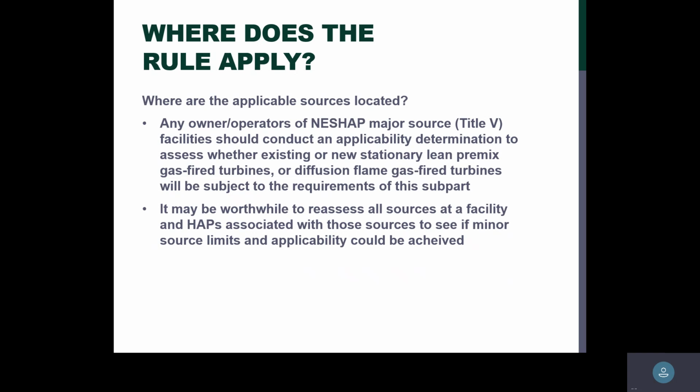One of the issues is that these turbines that are now under applicability of this rule have never been sampled, never been looked at before. So operators really don't know what they're dealing with as far as what their emission limits are going to be. And then outside of testing contractors, getting the oxidation catalyst and controls to reduce your formaldehyde on these turbines could also be an issue from an industry standpoint.